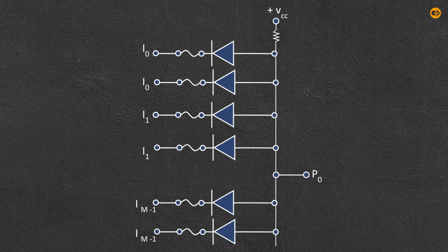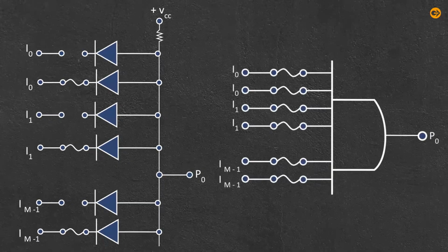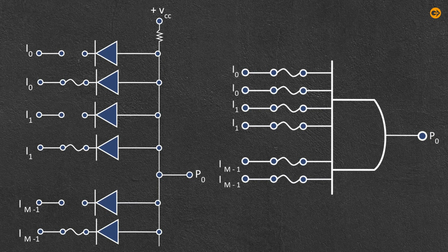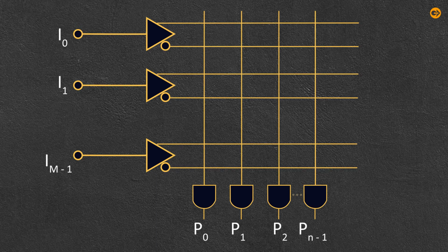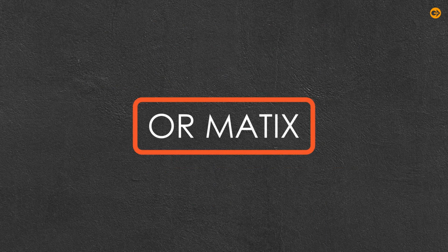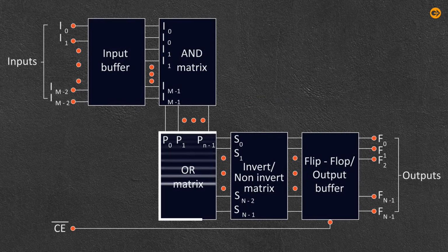it is in logic 0 in a non-programmed device. For generating the required product terms, the unwanted links are opened by the method of programming by the programmer in case of a field programmable logic array, FPLA. A section of AND matrix is shown with its equivalent logic representation. The below diagram shows the convenient method of showing input buffers with AND matrix and the interconnection is marked as X's.